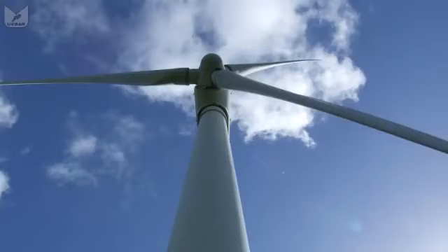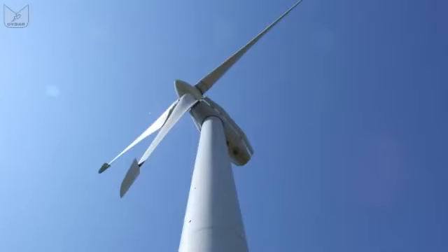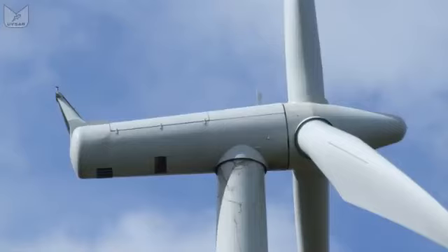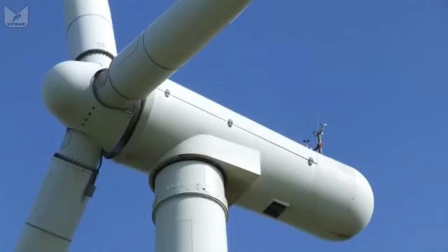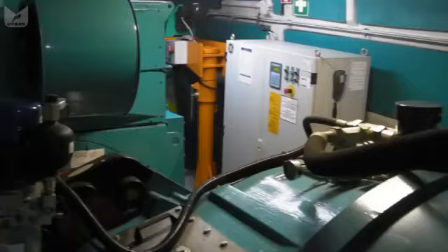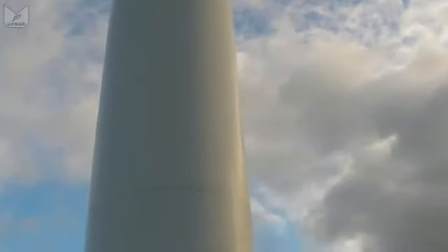Welcome. In this video, we'll show you the layout of a typical wind turbine generator as found on wind farms across the world. Now, exact designs do vary, but almost all the turbines in use today are horizontal axis machines, which have a 3-bladed rotor spinning in a vertical plane attached to the front of a box which we call the nacelle, after the fairing around an aircraft engine. And in this nacelle we have the generator, often a gearbox, and occasionally a high voltage transformer, and the whole thing sits on top of a tower, which is mostly there to keep the blades from digging a hole.